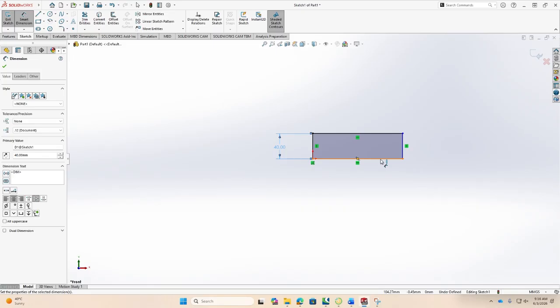Now the length in this case really does not come directly in our analysis because we are not looking into compressive buckling, right? So in this case, it can really be taken as anything, but because in the problem I have given you already 120, right? When I was choosing that, my only objective was to keep the length almost 3 times the width so that the assumption of having an axial member is satisfied. So that was the thing in the back of my mind when I chose 120.